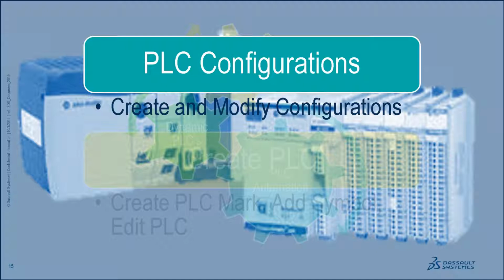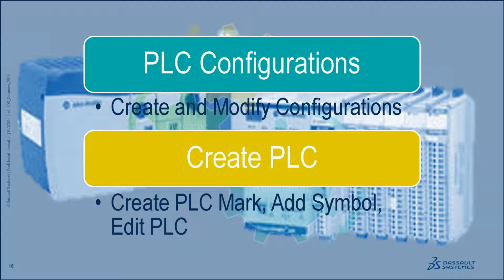So when it comes into the dynamic PLCs, we're going to first start by talking about the PLC configurations. Essentially, we're going to look at creating and modifying configurations, which in this instance are essentially template files that standardize the appearance of our generated PLC modules and any associated drawings that we might use for the automation phase. And again, these are a way for us to achieve standardization, capture that, and then use it as a repeatable configuration going forward. And then we're actually going to talk about how to create the PLC by creating a PLC mark, adding the PLC symbol, and editing it, all with the dynamic PLC tool.